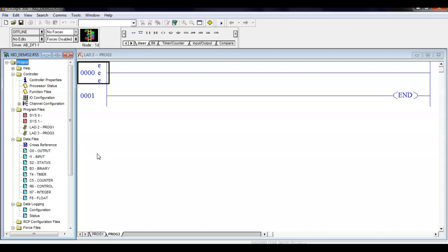On newer applications, you control the memory. So as soon as I have this binary file right there, even though I only need one bit, I lose 256 words of memory, or 512 bytes of memory. So for every bit file I create, it's going to eat up 256 words of memory.